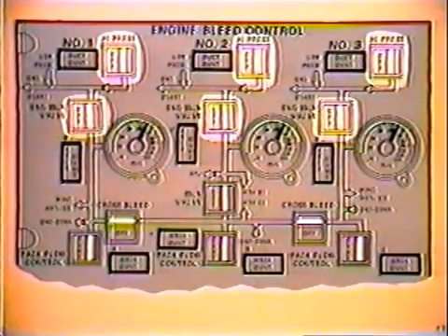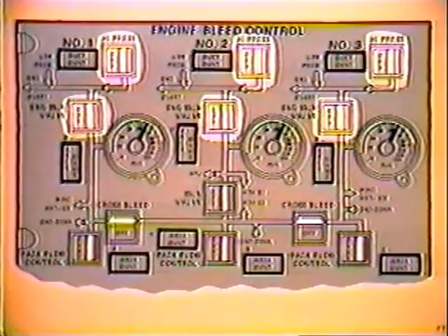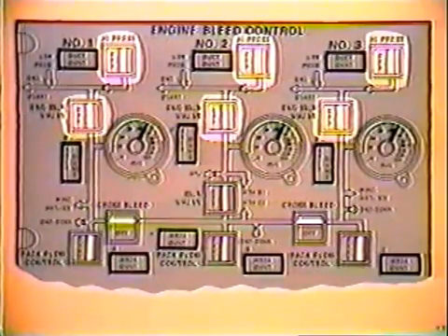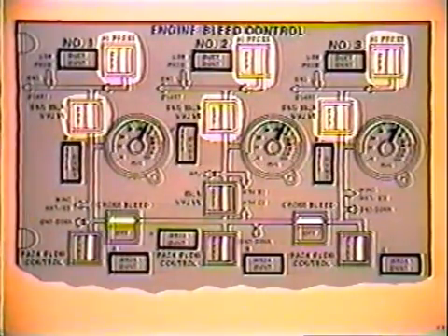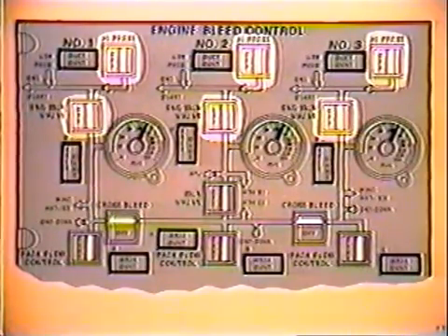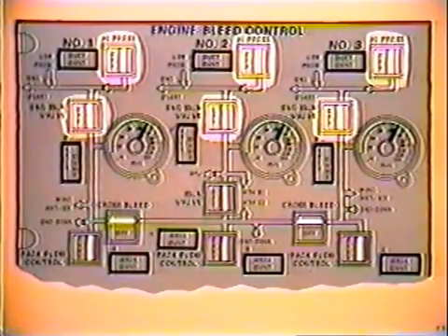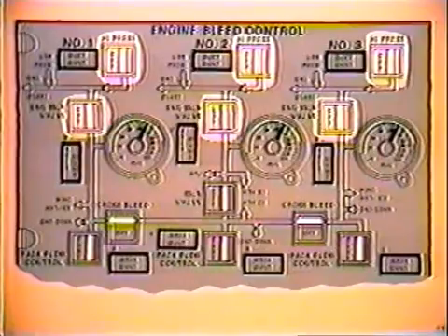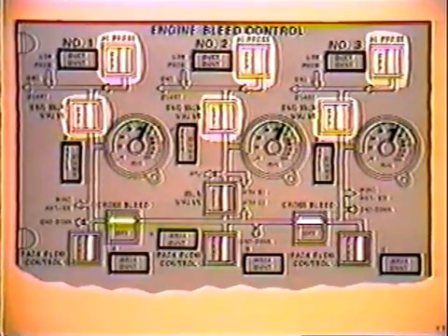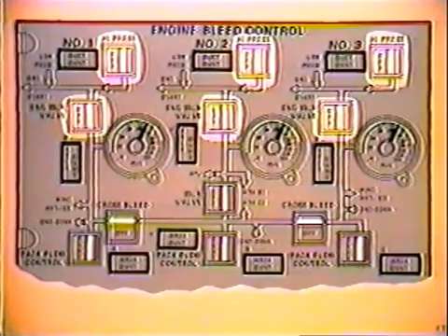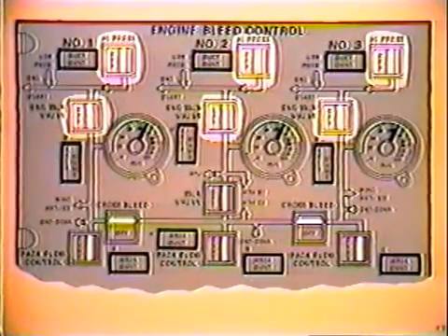With these switch lights latched, both the high pressure and the engine isolation valves are electrically de-energized and armed to open automatically with pneumatic pressure. The engine isolation valve will open when low pressure air is available. The high pressure valve will open when high pressure air is available and the pneumatic system demand requires additional air pressure or a higher temperature. The high pressure valve will close any time that the engine isolation valve closes for any reason. The flow bars on these switch lights will illuminate any time the respective valve is open.